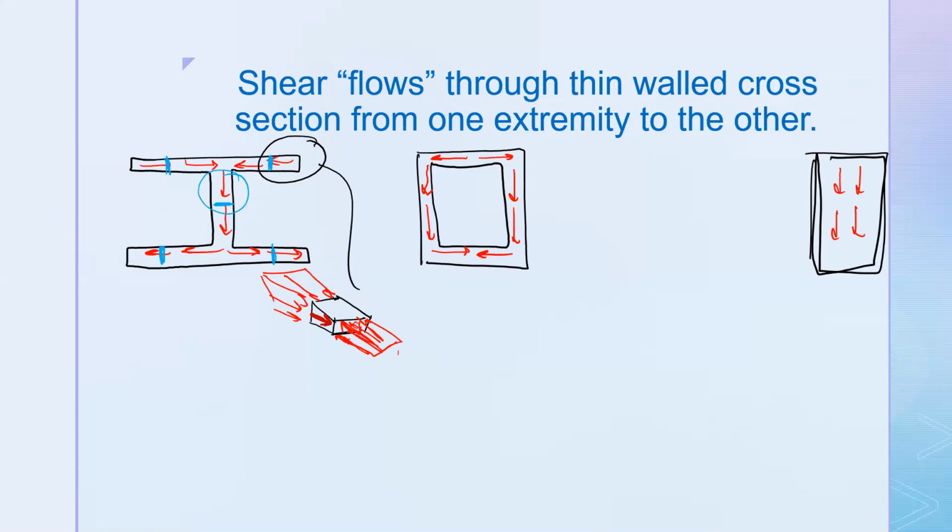And actually, I think I misspoke when I said that loading it upward would give you the opposite. The direction of these arrows is going to depend on whether it's experiencing positive or negative shear stress. So for example, if you have a beam with loading, so this is your beam and you have your loading, let's just say it's distributed loading. The shear diagram for that is going to look like this, right? And so part of it's going to be positive, part of it's going to be negative. So it just depends which portion of the beam we're looking at.